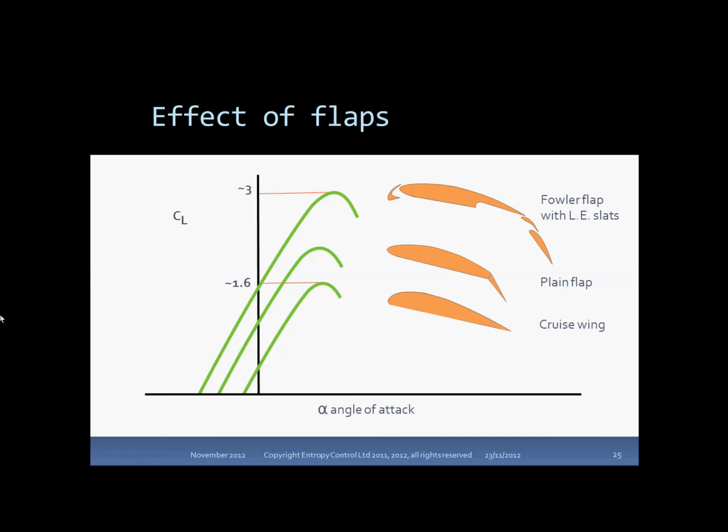But the most important effect is that the increase in wing camber increases the lift coefficient at any given angle of attack. This allows for reasonably high lift in a decent nose-down attitude, so we can see over the nose for landing. Concorde, not having flaps, has to land very nose high, and that's why they had to have the droop snoot for the pilot to see.